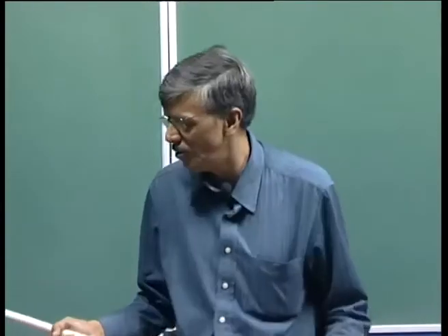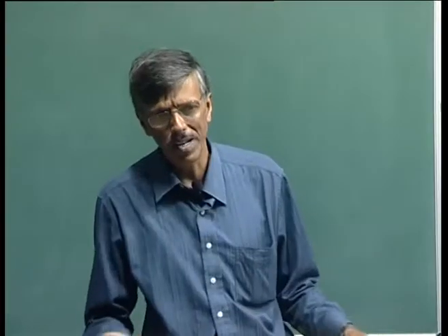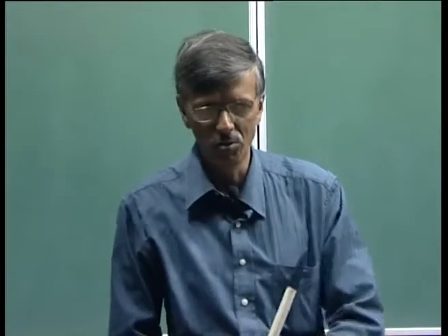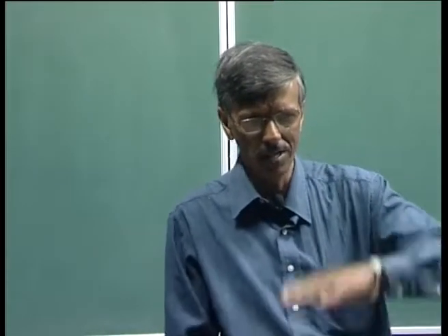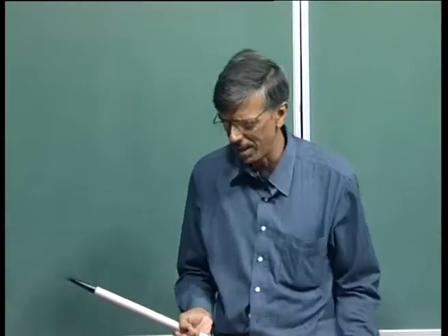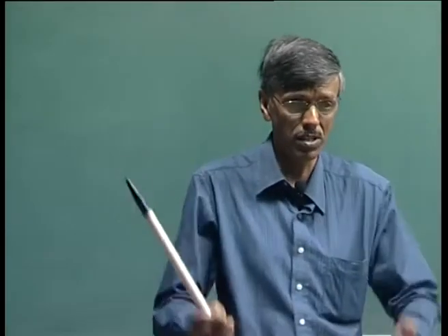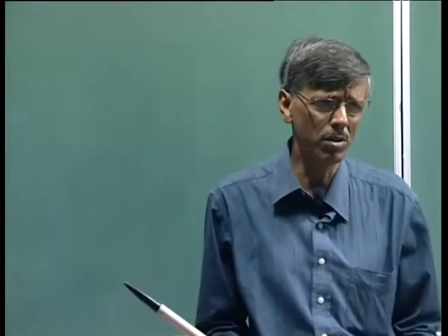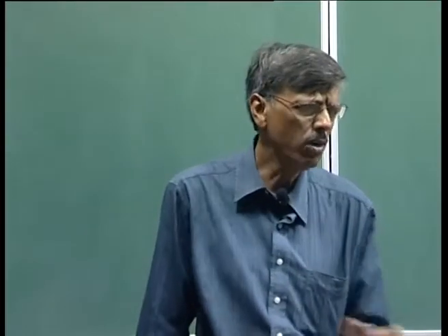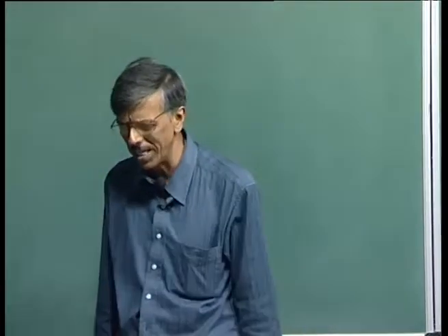So basically now we find two disparate things. On one side you have the experiment of G.I. Taylor repeated by Mike Gaster, which was showing this boundary layer heaving up and down. And then there was this experiment done by Klebanov in the late 50s, where the whole boundary layer was once again seen heaving. But then you're talking about free stream turbulence. It's not a monochromatic excitation like vibrating a bump. So how are these two disparate things unified? That is what we started looking at.